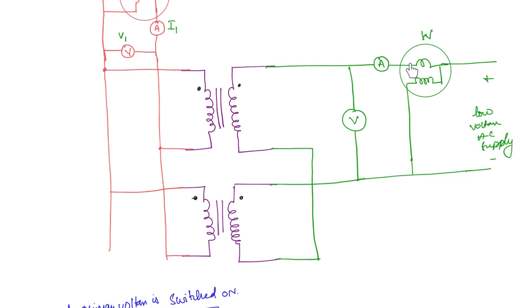So now when the current is flowing through the secondary, this is being energized, so this will become the primary. Now when current is flowing here, you can see that the voltage source here is short circuited. That means this and this will now be at the same potential, which is nothing but a short circuit test. So it is behaving similar to a short circuit test. You can mark the current direction. This is the short circuit current.